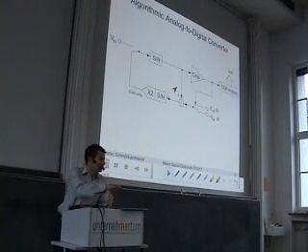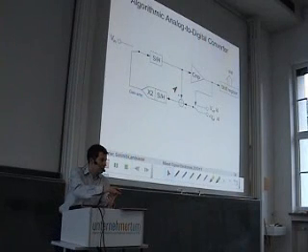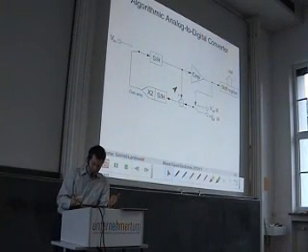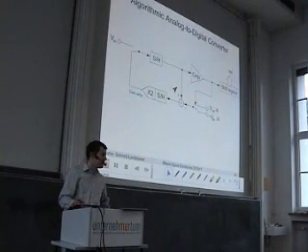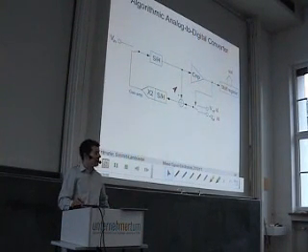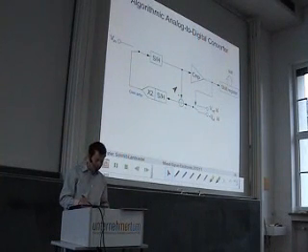Still the basic components are a comparator, of course the sample and hold, something that subtracts a reference, Vref over 4 or minus Vref over 4, and a circuit that doubles the remainder.